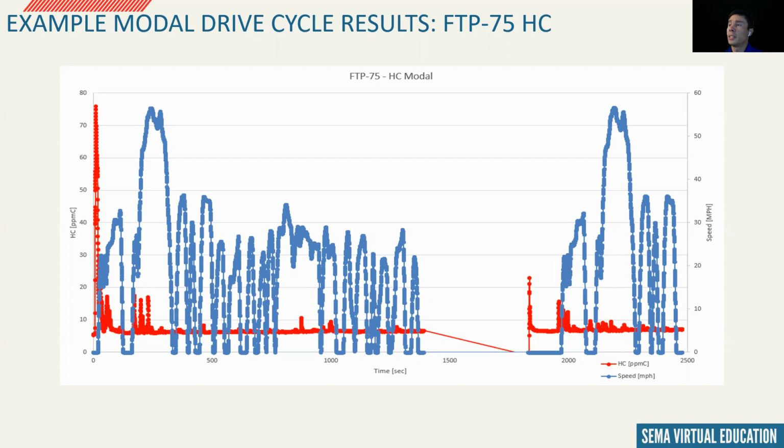During the second set of accels or hills, you will see we have some hydrocarbon spikes. This region right here. This is an inherent hurdle during phase 1. We need to produce a fair bit of torque in this scenario. The engine is cold, and the driver will be inducing transients to stay on the target speed.